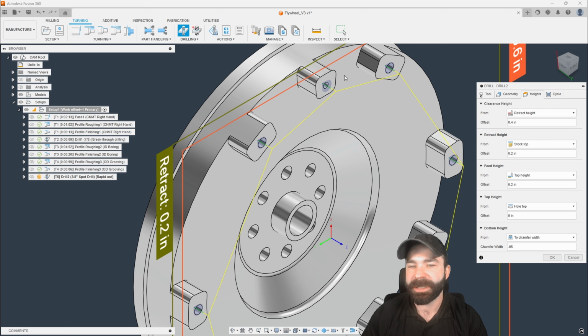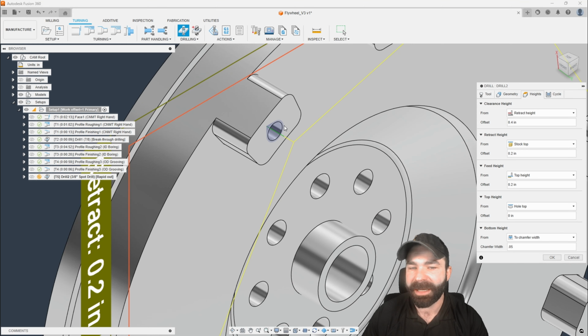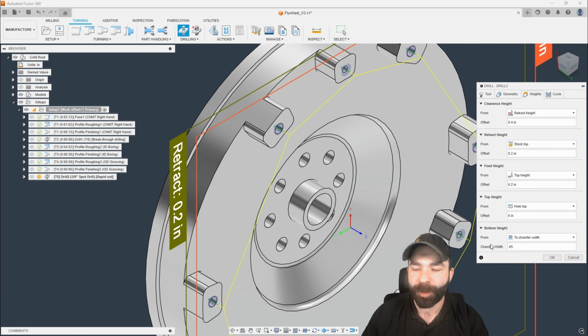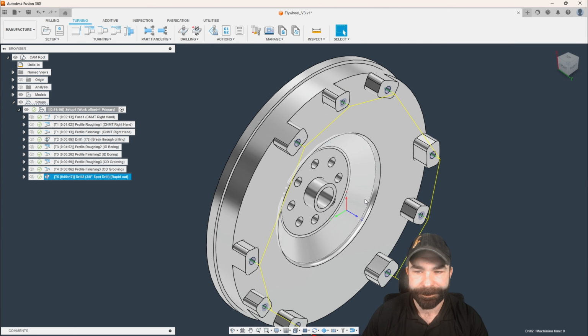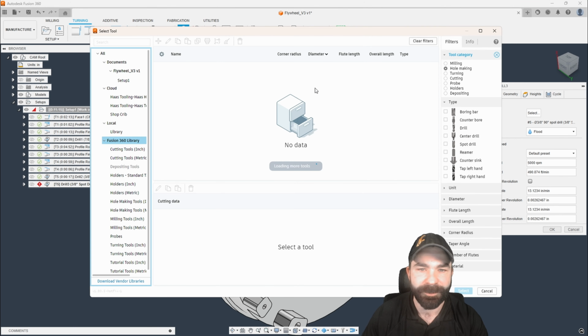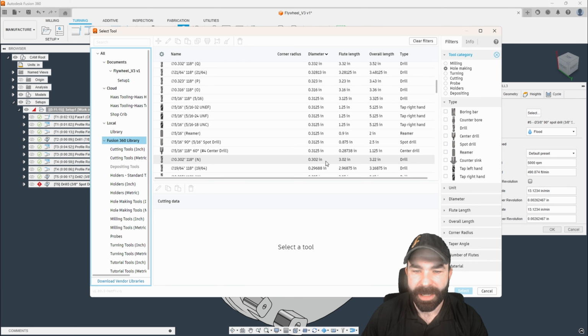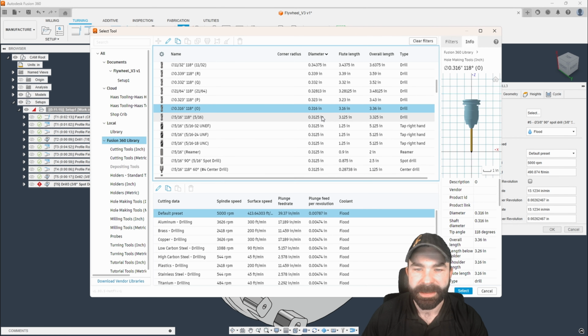So I may split them up into 2 separate cycles. But as you're seeing, based on the defined areas of my tool, I can chamfer this when I spot drill it for drilling, right? So again, now we go back, we say drill. I need a 315 drill. So let's go grab a 315 drill. I'm going to scroll down and we have a 3125, 316. Again, based on if that's a tapped hole or not, you guys are going to define that accordingly, of course.